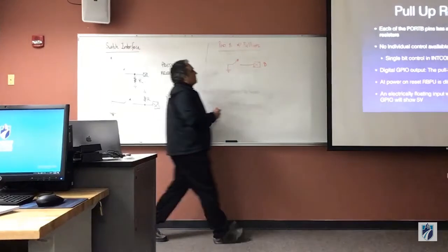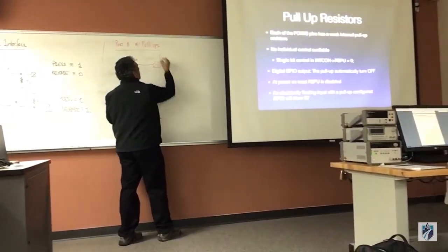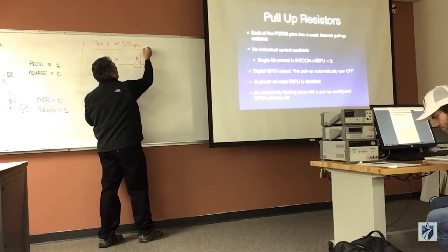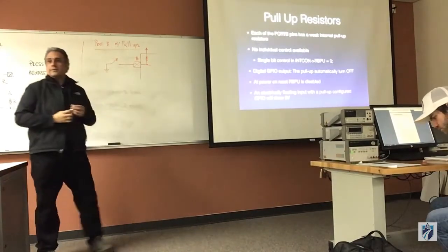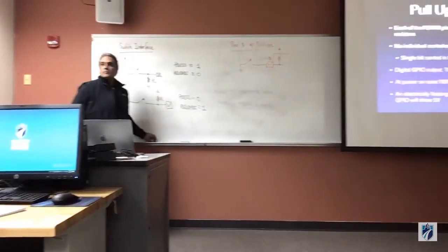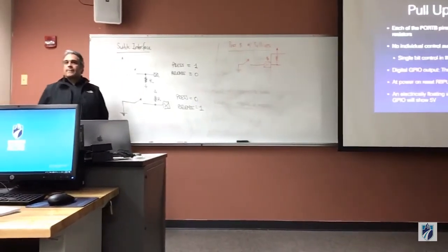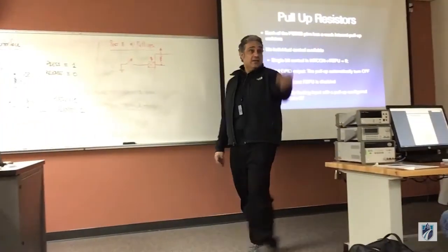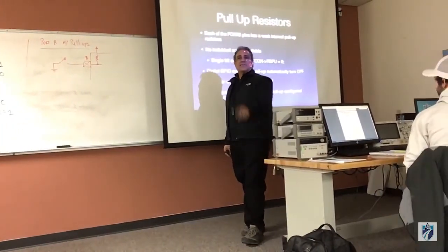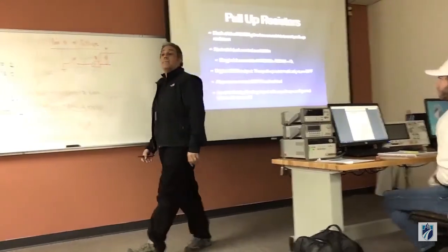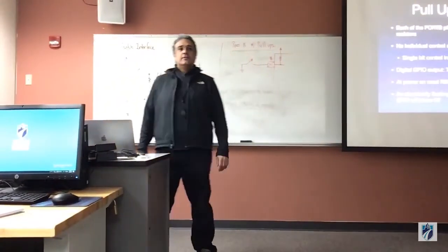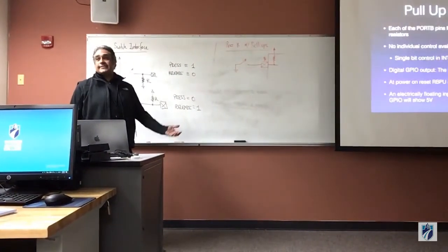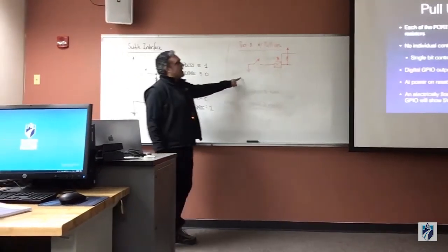So you can think that inside of the microprocessor, inside of the micro, they did this. See that? Why is this useful? Well, I save incredibly in parts. If I have 2 push buttons and I'm pumping out 10 million units, it makes sense right away. It's way less parts, it's simple to manipulate, and so I know already that I have my pull-up resistors.